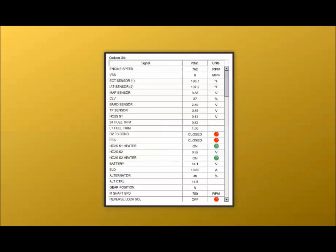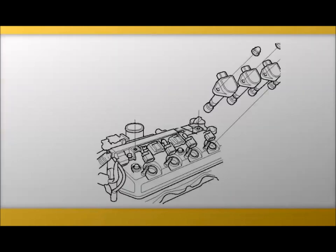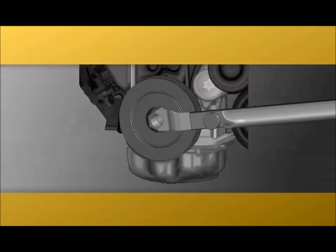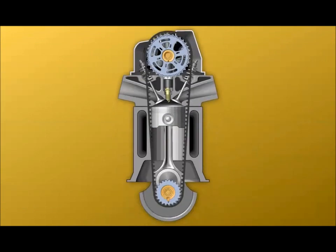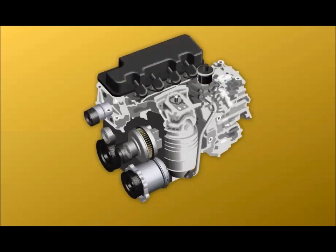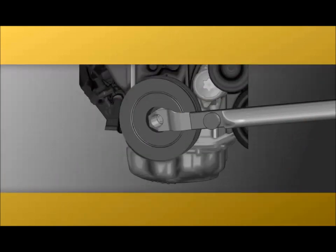The scan tool data may also show that the misfire only occurs at a specific RPM or with a particular load on the engine. If you suspect a problem caused by internal binding, remove all spark plugs and rotate the engine by hand. Be sure to rotate the crankshaft at least twice in case the binding is present in the camshaft bearings. If you feel binding during this test, remove the accessory drive belt and test the engine again.